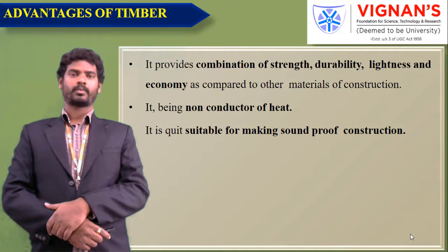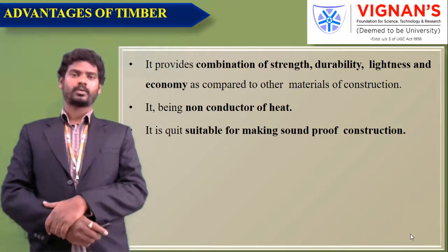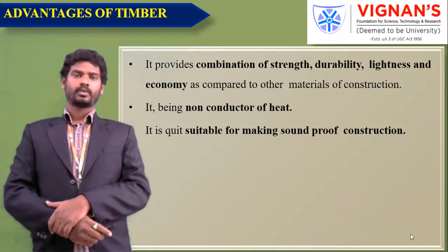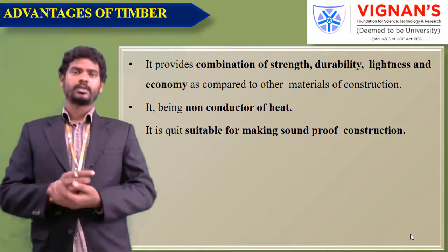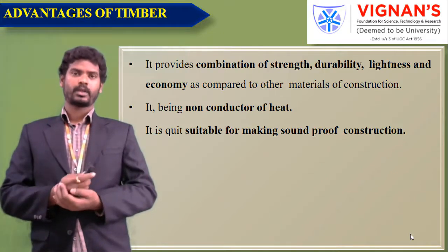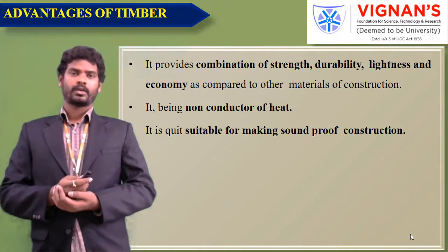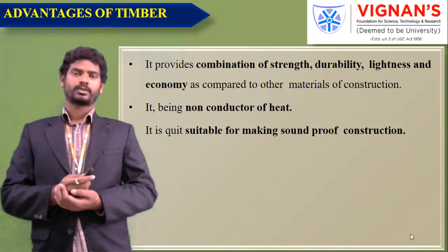Being non-conductive of heat, it provides a combination of strength, durability, lightness, and economy as compared to other materials of construction. It is quite suitable for making soundproof construction. That's why in auditoriums and cinema theaters and for other soundproofing purposes, we can use wood as one of the materials. This is one of the advantages.